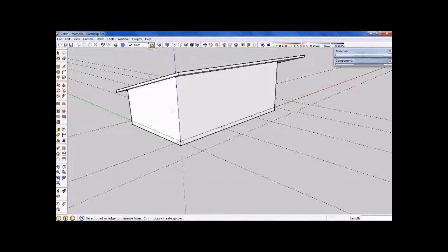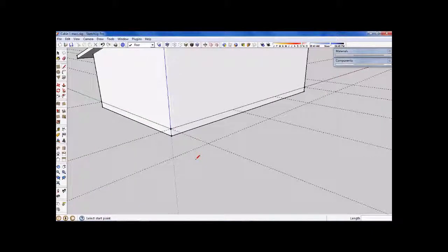I'll change the layer selector back down to floor, because we're going to be creating a floor here. I'll grab my pencil tool, I think might be the best. There's probably a couple of ways of doing this, but I think initially I'm going to start drawing this from the existing floor level. After I've drawn it up at this datum level to start with, I'll then move the faces down. So I'll draw from this corner of the building at floor level first, out to our grid line,